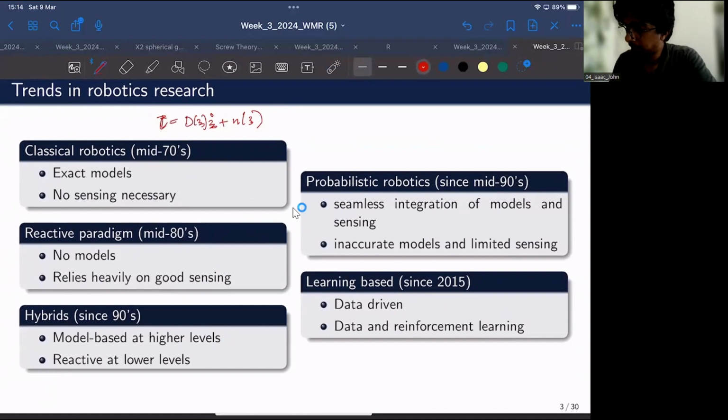PID control would simply mean we would give a control signal that is the sum of a term proportional to the error, then the derivative of the error, plus the integral of the error. Each of these terms in PID has different relevance.